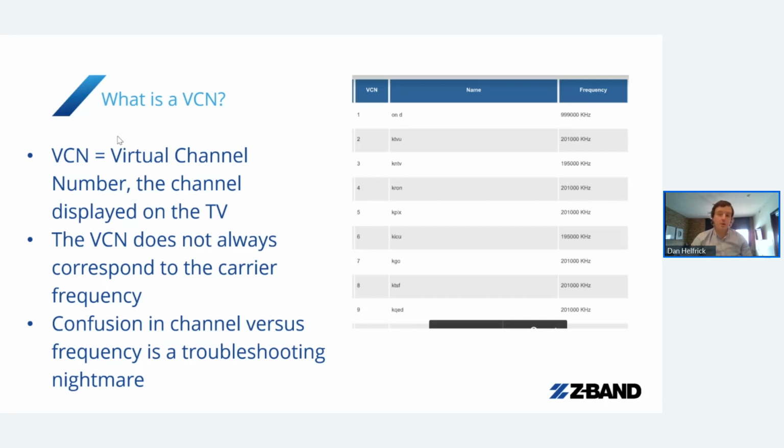To be really transparent about this, more and more with service providers and their ability to compress content, H.264, H.265, continually make things smaller, they're actually taking up less and less bandwidth in terms of RF frequencies than what they had been to deliver you more programming. So there's a lot of channel lineups that we see that are stacked, kind of like you see here in this image on the right hand side, where you're fitting three, four, five programs onto one 6 megahertz RF channel, and you're actually being able to deliver 100 programs of content in 25 or 30 RF frequencies, which makes it